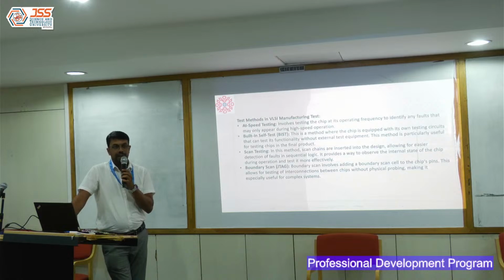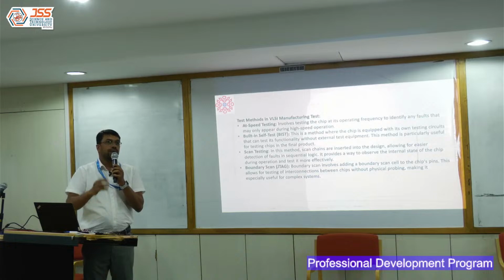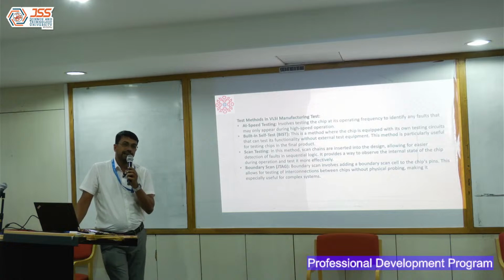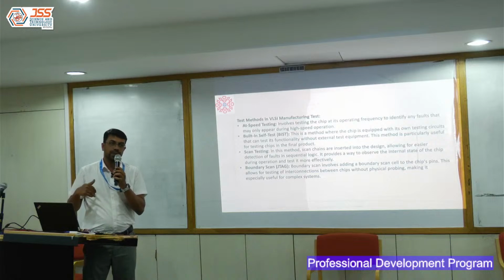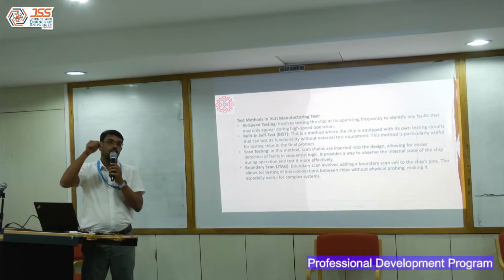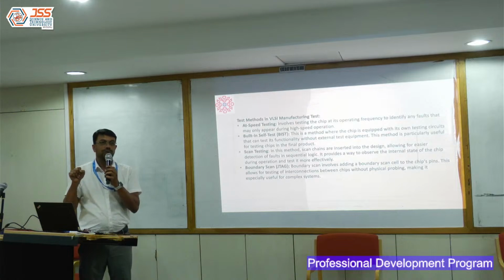So this PLL, there is something called as PLL locking sequence. You have to lock the PLL. Once you lock the PLL, the output would be whatever frequency you have programmed that PLL to. Now the PLL output would be a continuous train of pulses. We have something called as at-speed testing, wherein we shift at a slower frequency, which we call the shift frequency, but capture at speed. Now, how do you select between your shift clock and capture clock? So that's where a concept of OCC comes into picture, on-chip clock controller.